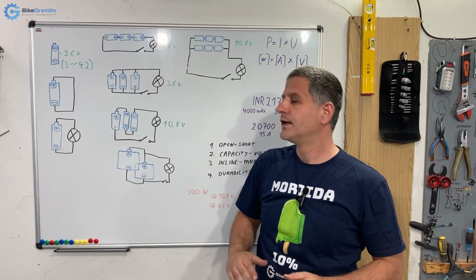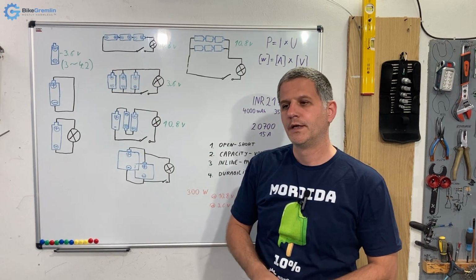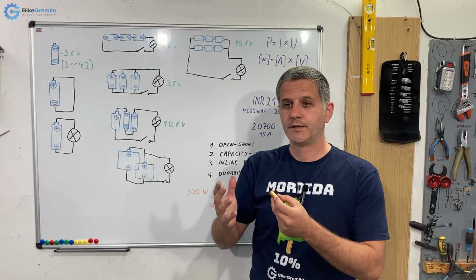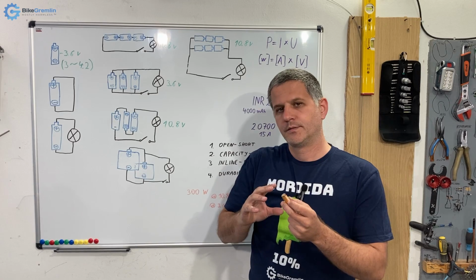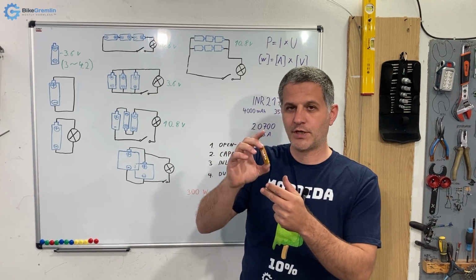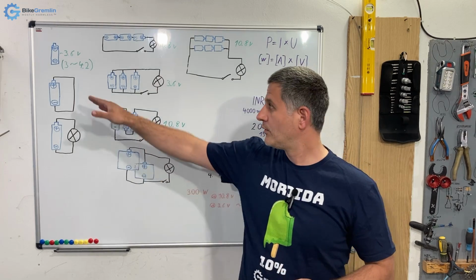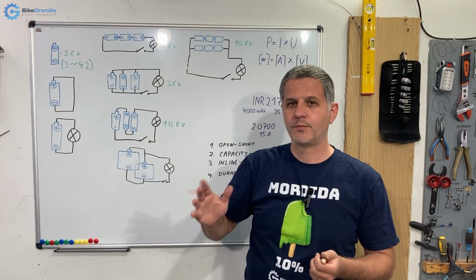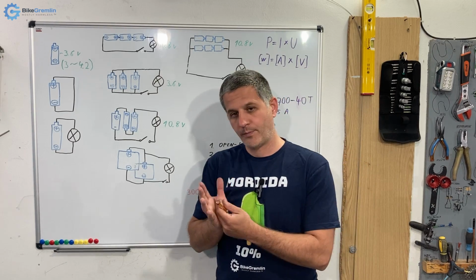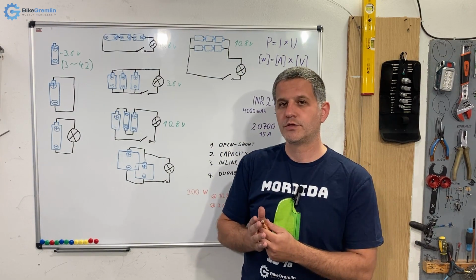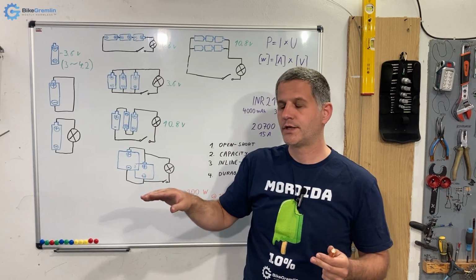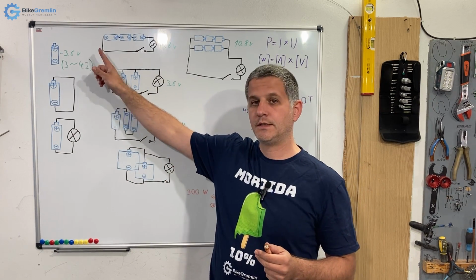When you keep discharging it, it also loses the voltage. The voltage drops, and when it drops past a certain point, the chemical processes inside the battery that create voltage and are recreated, refreshed when you recharge rechargeable batteries, stop working. If you go below a certain voltage, you might cause some permanent damage and destroy your cell. Smart appliances and chargers won't let you drop below a certain voltage, the appliance will shut down, and they will not let you exceed the upper limit.